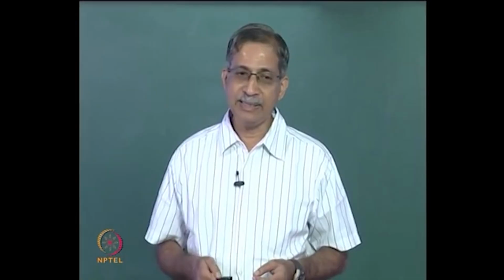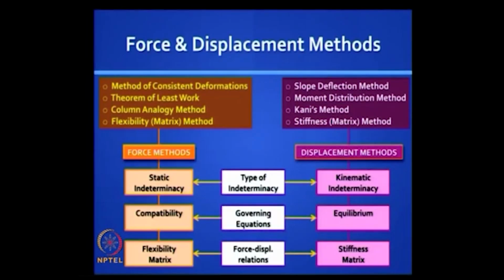Secondly, to solve the indeterminacy, you need to apply some equations, which are called governing equations. As you know very well, in force methods they are of the nature of compatibility equations, while in displacement methods they will be of the nature of equilibrium equations. And you need to express the displacements in terms of forces. You can do it 2 ways. You can either use a flexibility approach, where you deal with the flexibility matrix, or you deal with the stiffness matrix. So these are broadly the fundamental differences.